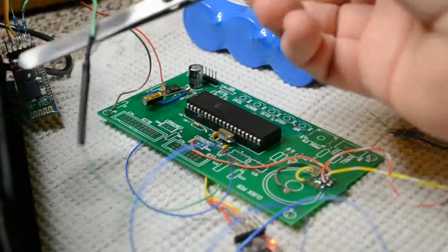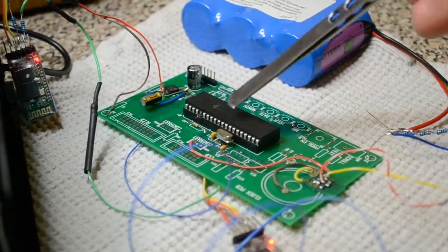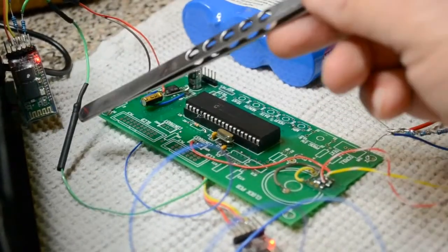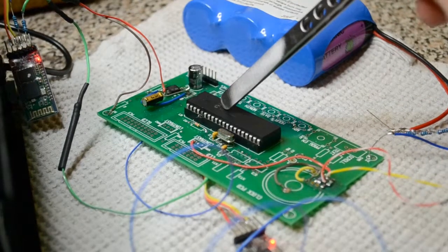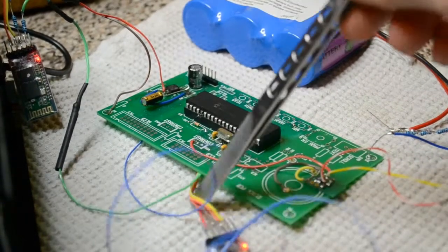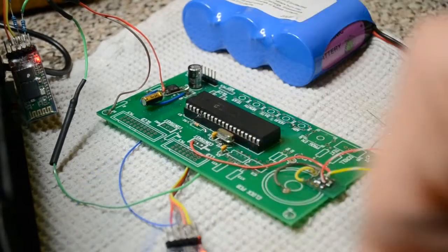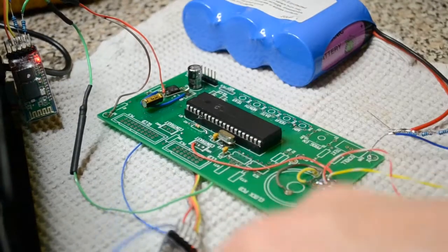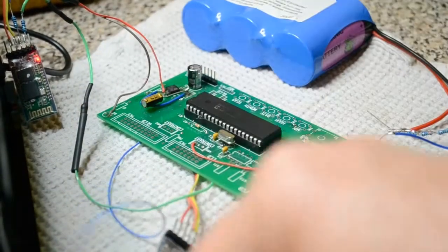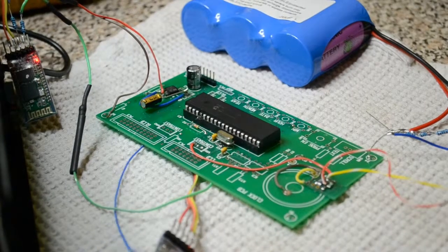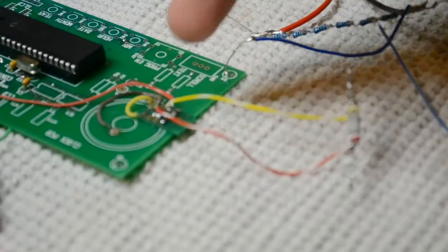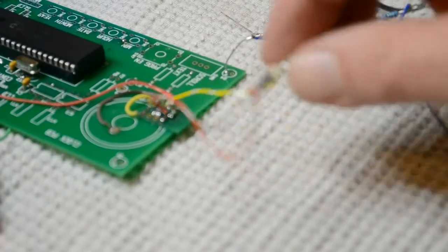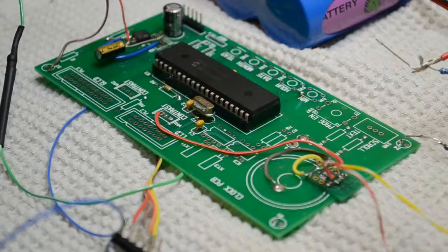Right, so this wire tells this PIC microcontroller from the clock, every 5 or 10 seconds past each minute, a pin goes high on here, and this transmits the UART via this second Bluetooth UART transceiver. Transmits that to my microcontroller, which is obviously down here. This obviously normally lives upstairs. This bit here is the analog devices with my current shunt, and that converts the current to voltage. As I said, see the other video.